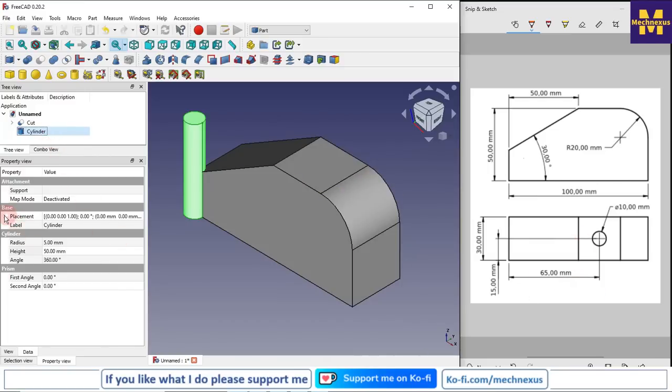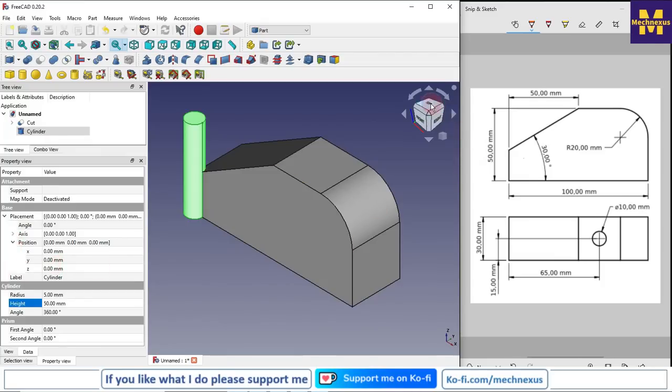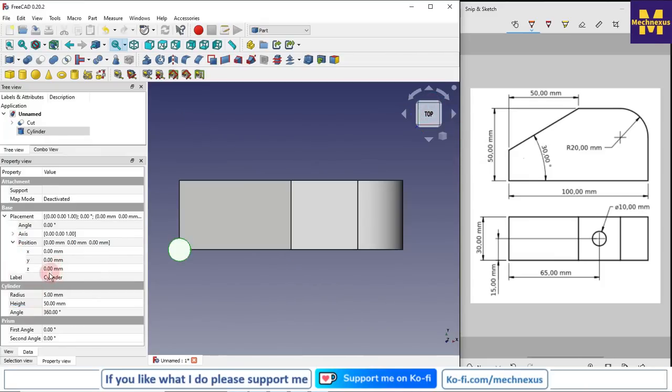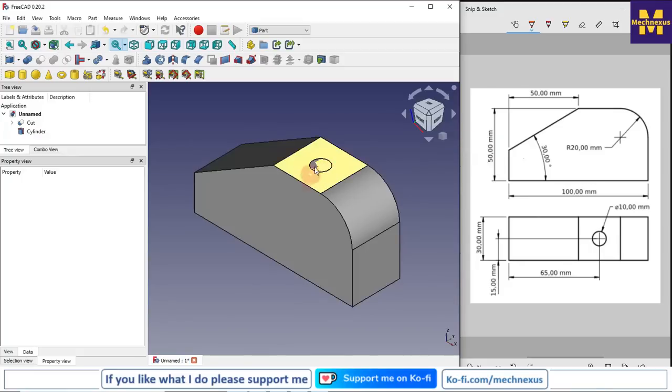So I will go to the placement and I will move to the top view. From here to here it is 65, and we see our coordinate system is x, so we will give the x 65. And then on the y axis it is 15, so we will go to the y and give dimension 15, and we will switch to the isometric view.